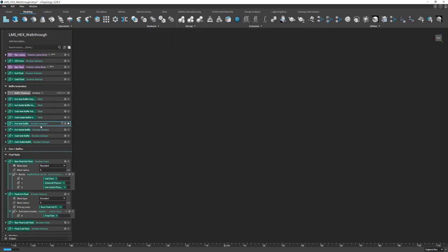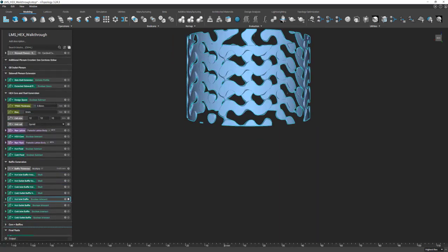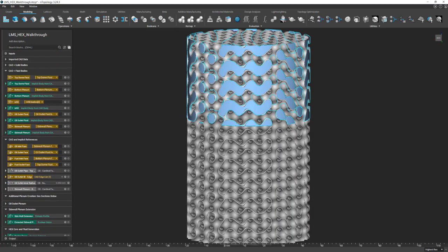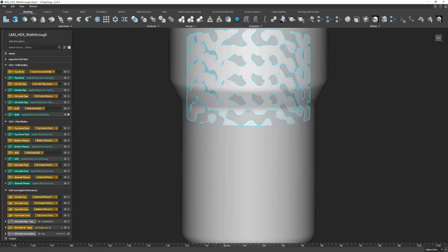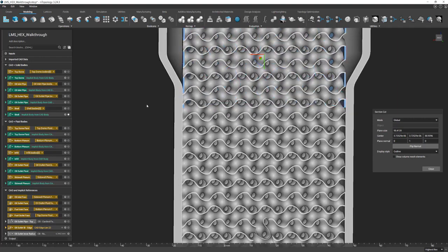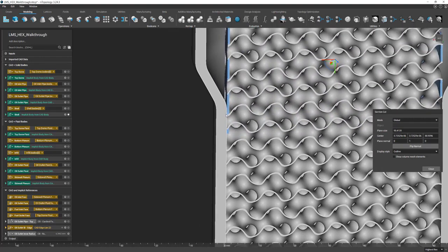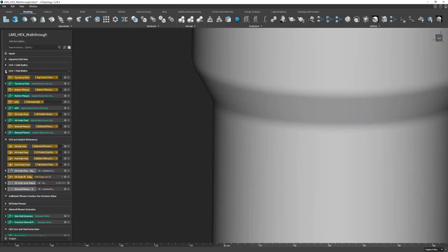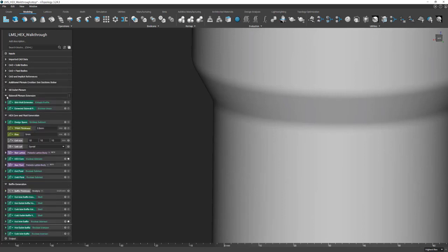And if we look now at the hot inlet baffle, the hex core, and our shell, look at a cross section. Remember, our whole goal was to just extend this baffle down beyond where the fluids would be forced to mix. Closing the cross section, I'm going to minimize the sections.